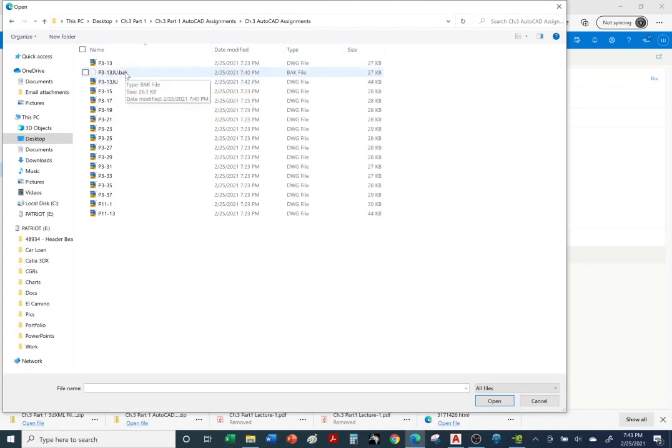Notice it created a backup. Okay, so if something ever happens to your original .dwg file, if it gets corrupted, something goes wrong with this file, you can always use this backup. So even though it's only 2 minutes older than the final one, if you're gonna email me this one as the backup one, just in case this one got corrupted, you have to go in there and change the BAK to .dwg.